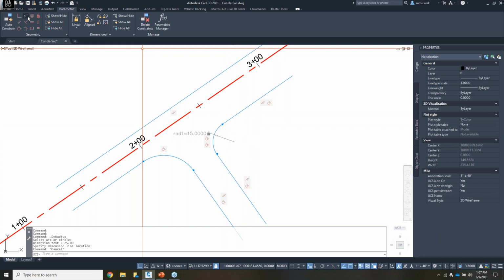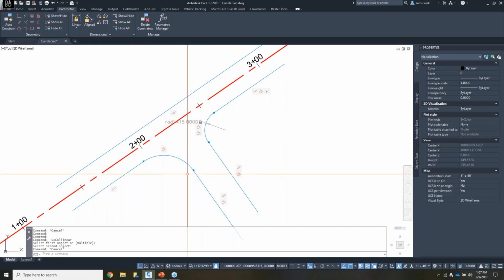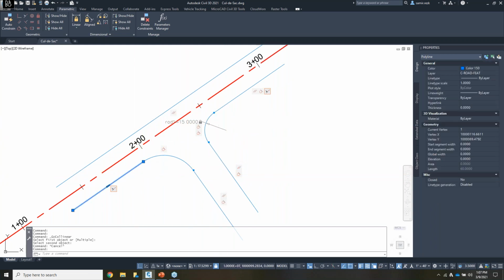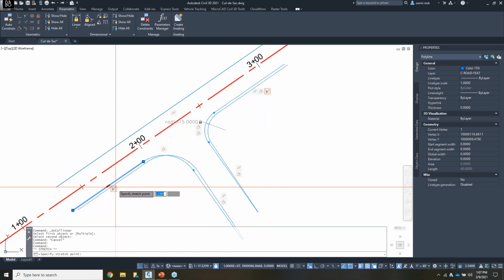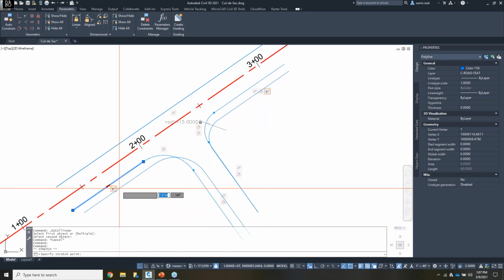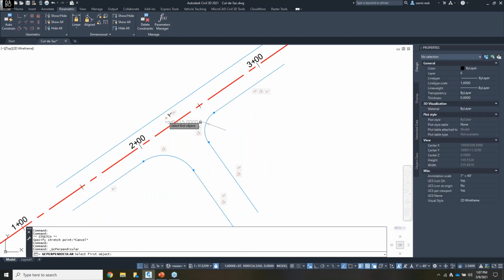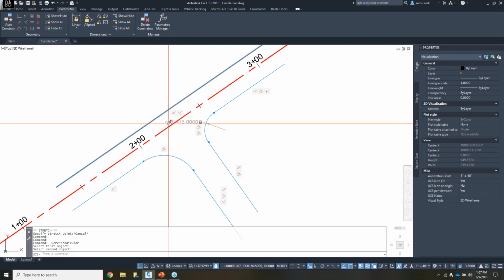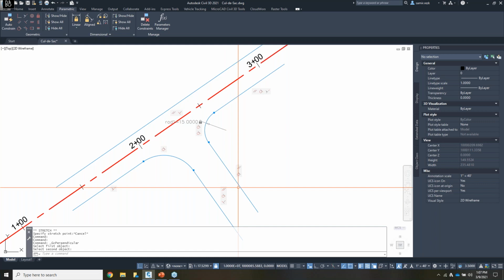And perhaps I want those two to be coincident or collinear, so they stay collinear together. Now if this changes, the site changes. All right, so I'm not constraining it enough at the moment to keep it from changing too much. If I can do that one perpendicular to that one, we can keep continuing to constrain it that way.